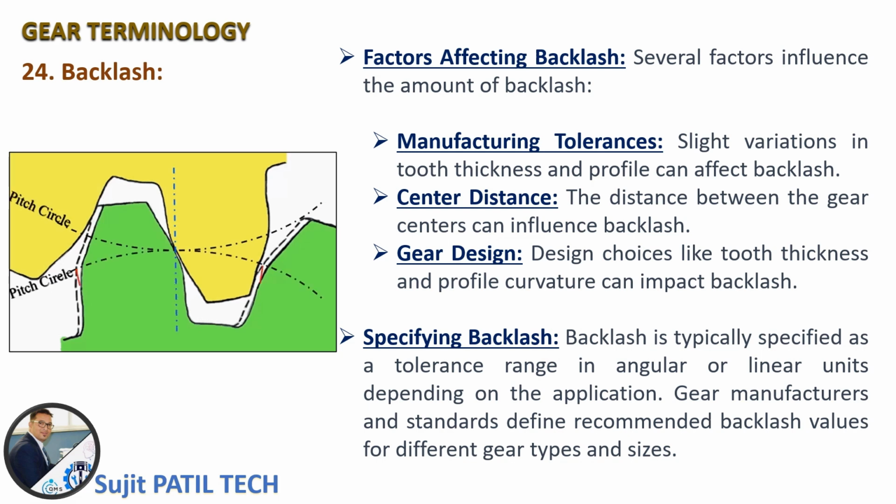Factors affecting backlash. Several factors influence the amount of backlash. Manufacturing tolerances: slight variations in tooth thickness and profile can affect backlash. Center distance: the distance between the gear centers can influence backlash. Gear design: design choices like tooth thickness and profile curvature can impact backlash.